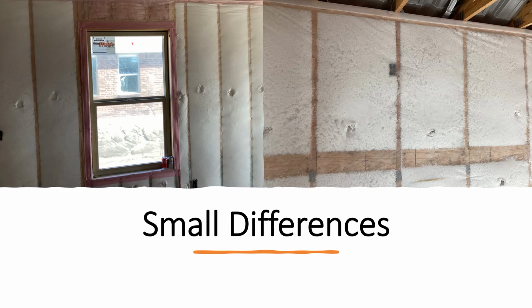So in my opinion, the left is a grade 1 R15. On the right, if it's R13, I'd probably list it as a grade 1 because it's fully filled and it will be in contact with all 6 sides. However, if it's really not that dense, you might question whether that is really meeting an R13.